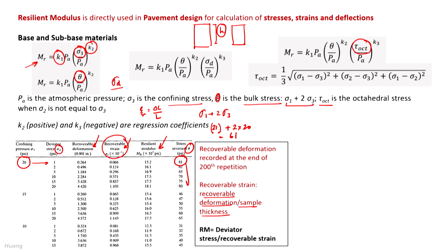Likewise, you can do all the calculations. You can also keep a record of the response corresponding to the change in stress invariant. Then once we complete a given confining pressure, we increase the confining pressure, and at that fixed, increased confining pressure, we see what happens when the deviatoric stress value is increased.